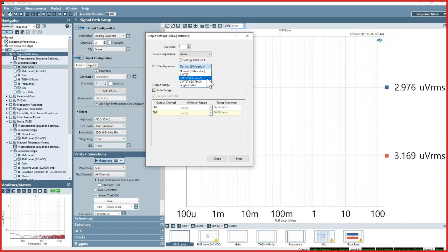In the IEC version of the common mode test, the two legs are actually unbalanced purposefully by a small amount, a few ohms, to more realistically simulate, I'll say, an off-the-shelf transmitter, which typically doesn't have perfectly balanced circuits. And then single-ended, which will actually just take the balanced output, the physical connector of the APX, and convert it into a single-ended device.